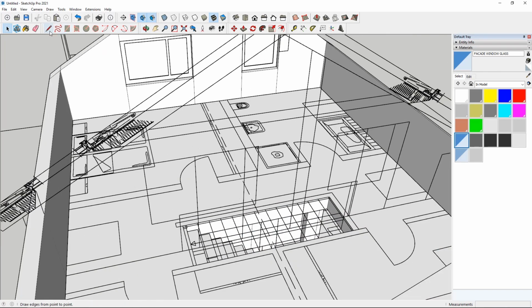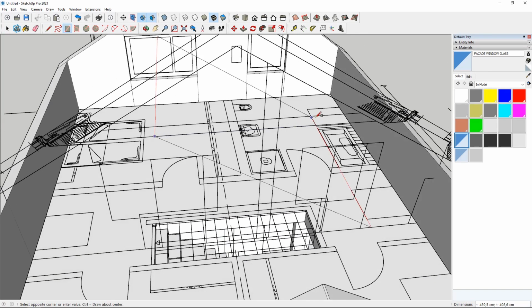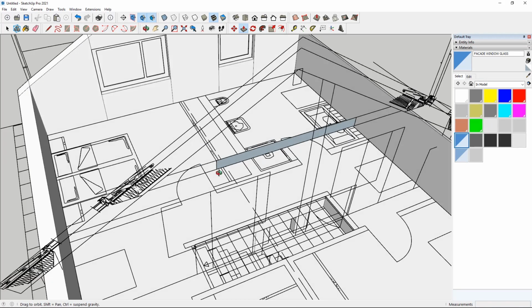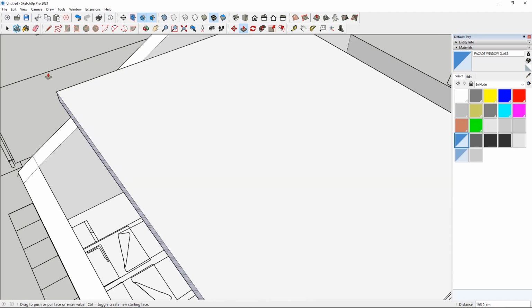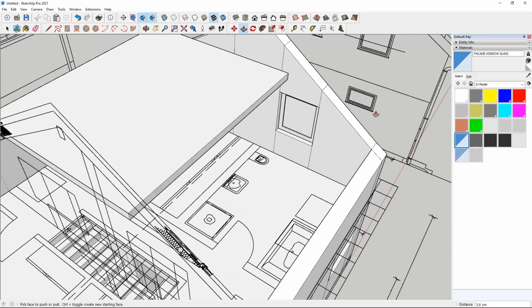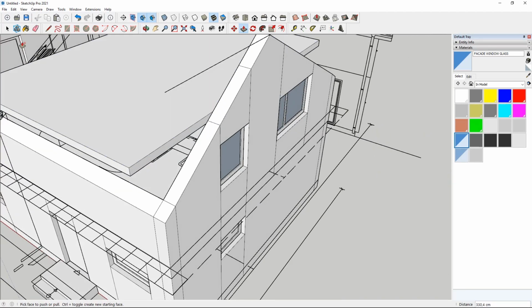Next up is the ceiling and the interior walls. Following the section drawing, we can model the ceiling by starting with a rectangle, then extruding it out to all sides and cutting out the pieces we don't want, as shown here.